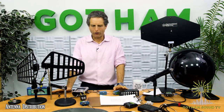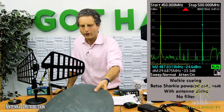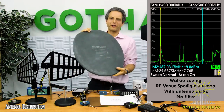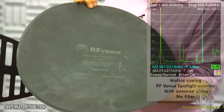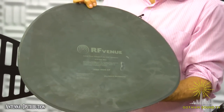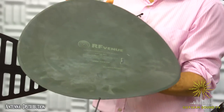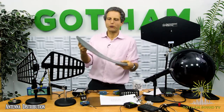So that's part of RF distribution. The other thing I want to show is we did some tests in the office with our spectrum analyzer, and here's an antenna that is a really interesting design. It's not appropriate for every situation, but it's the RF Venue Spotlight antenna, and it is basically designed for near field applications, right? If one of our themes is less is more, this is a way to get less.